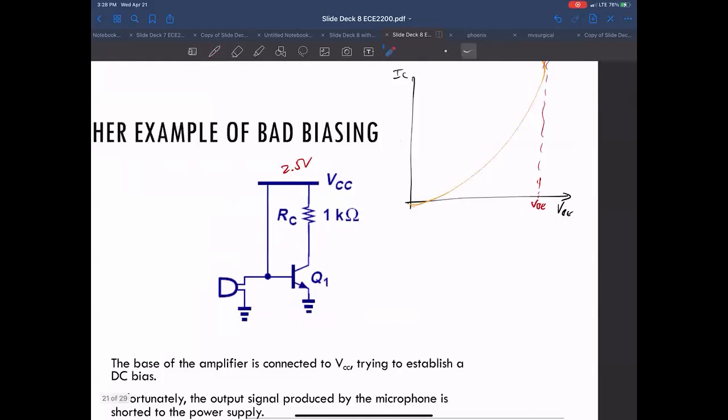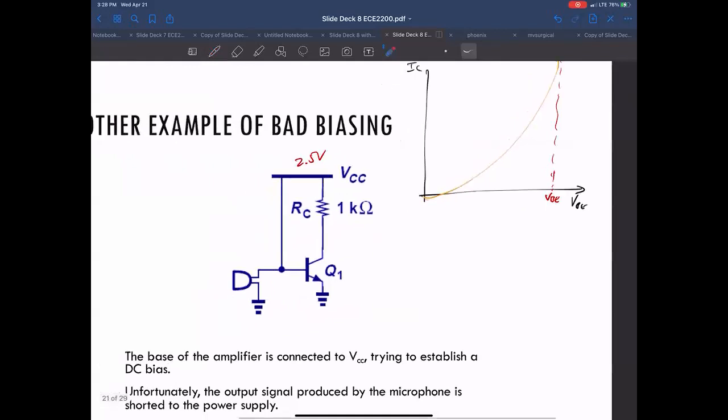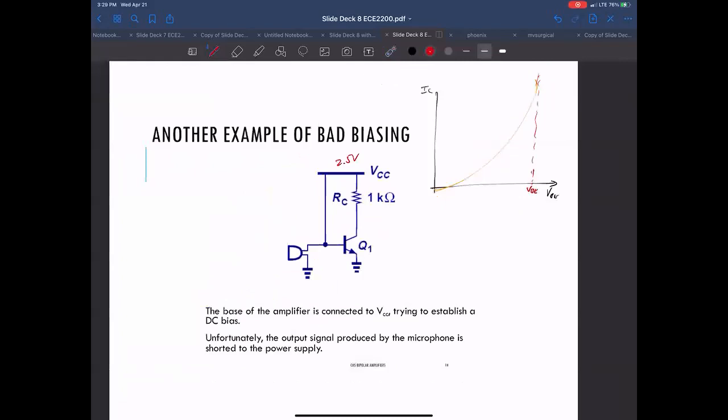In the previous lecture, we talked about 200 ohm as an example. So if you have a 200 ohm resistor from your signal to a dead short, really any resistance to a dead short, you won't be able to move this point at all. It's just going to be sitting at 2.5 volts, and it's not going to change. There'd be no modulation at the input of this device, so that doesn't work.